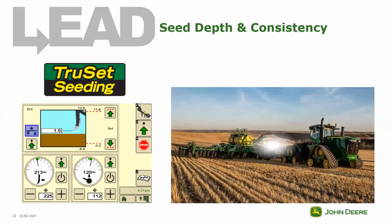John Deere equipment achieves consistent seed depth across the drill through its wing flex, which is designed for 15 degrees up and 10 degrees down on all sections of the drill, which allows for better contouring along the ground. In order to help better follow the ground contour, there's a floating hitch and tires within the frame, which greatly improves ground following. TrueSet technology controls, monitors, and allows operators to adjust the desired depth and pressure settings from inside the cab.